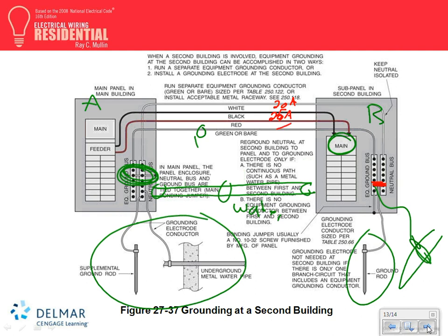So Spencer, if there's 20 amps coming in, one and the other, what's the difference between them? 5 amps. Look what happens if you bond them. I'm going to throw these numbers out based on nothing: of the 5 amps difference, there will be 4 amps going back on the neutral. And what happened to the other amp? 1 amp going back on the water pipe.